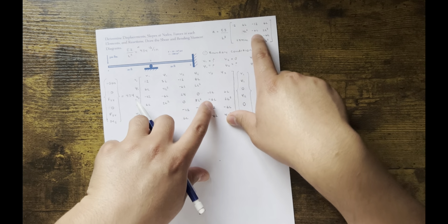So we're going to do equation 2 minus equation 3 will give me an equation 4, okay? So when you do that, 0 minus 0, that's 0, equals, this goes away, 4L squared minus 2L squared, that becomes 2L squared Phi1, right? That minus this, and then this one minus this one becomes minus 6L squared Phi2. So this is equation 4. All right, let's go ahead and bubble that up just to keep it for later.